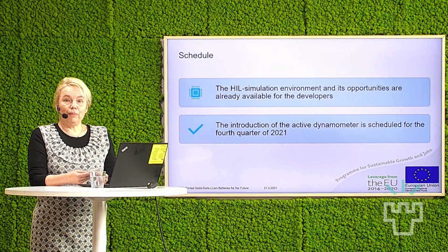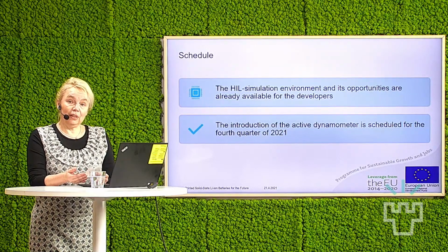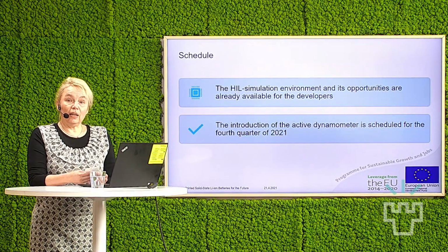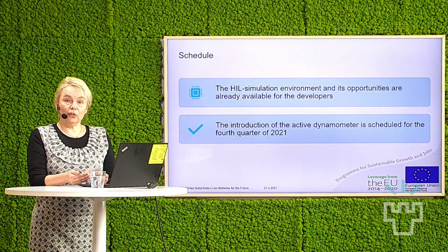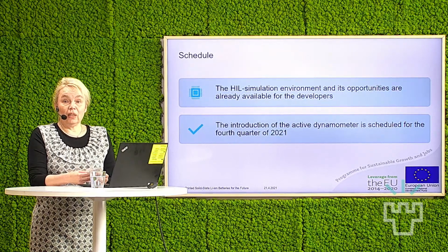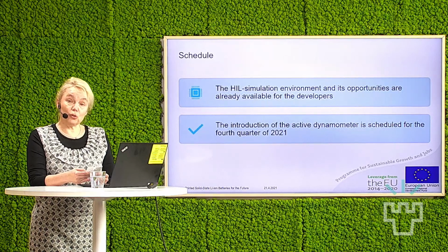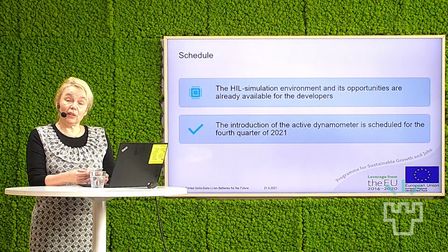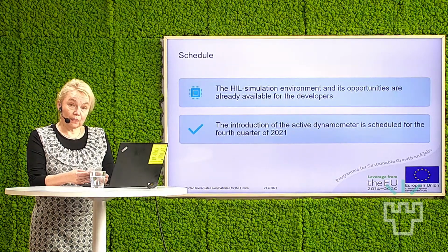We measured the ionic conductivity of the solid state battery electrolyte before we use it in the battery cell. And typically those conductivities we measure are higher than what we then see in the real battery cells. Of course, this is a key issue for the project also, and we can improve the conductivity also in solid state reactions.